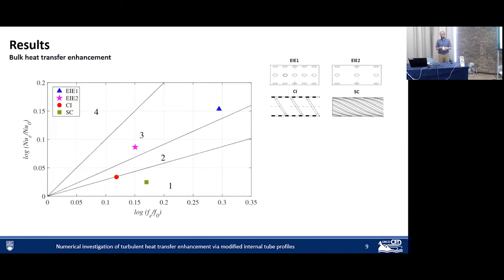The company that we were working with, its expertise is not so much on building these furnace tubes, but they develop a special coating. And that coating is a special catalytic layer that reduces the coking. And their benefit to the industry is we can provide you a coat with a special augmented shape of these structures and things. So not only are we reducing the coking problem through the catalytic chemical special sauce that we've invented, but we also improve your heat transfer rate and reduce your energy expenditures, et cetera. So that was the motivation here.